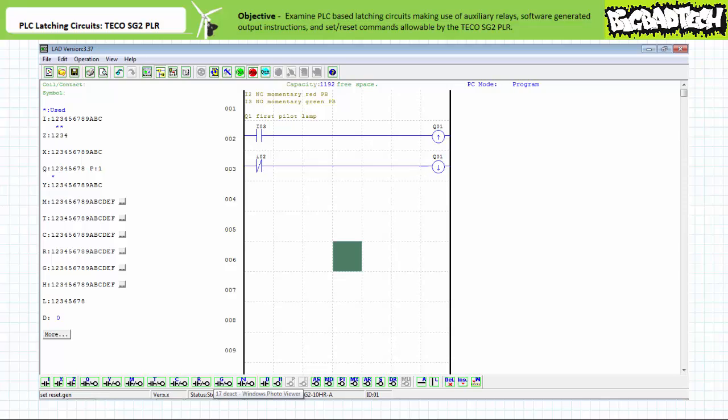You note that the break instruction in this scenario is necessary since the electromechanical nature of the field input device attached to input I2 is normally closed. You recall that the break instruction is essentially the opposite of the make instruction, and that a break instruction disallows logical continuity when input I2 experiences a logical 1, the deactivated normally closed state of the red push button, and allows logical continuity when input I2 experiences a logical 0, the activated held open state of the red push button.